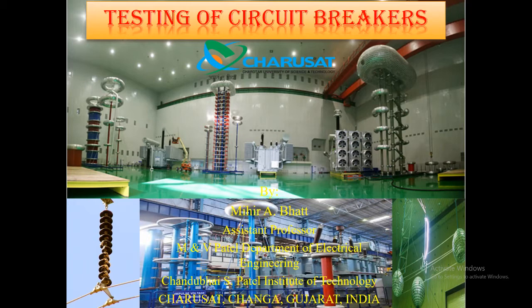Apart from the dielectric test, which is usually performed to assess the quality of the insulation, the direct testing and the indirect testing are conducted to assess the specifications and the performance of the circuit breaker. If one wishes to assess the performance of the circuit breaker, indirect testing is generally conducted, which consists of two different types. One is known as a unit test and the second is known as a synthetic test.